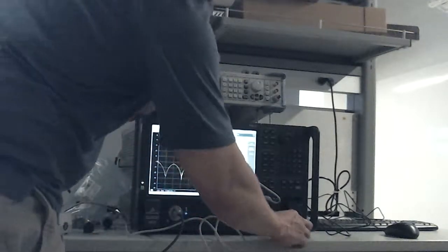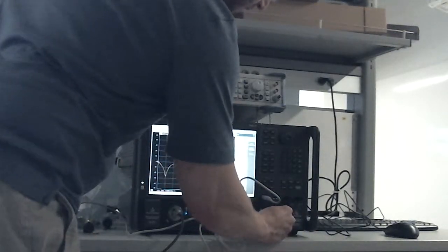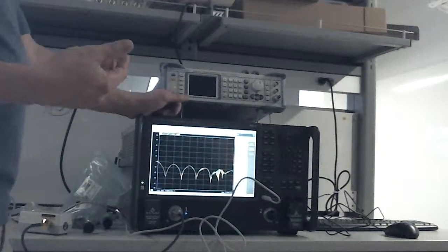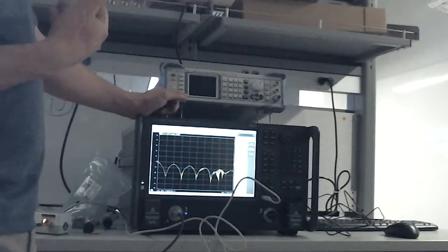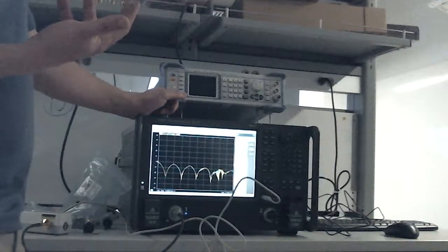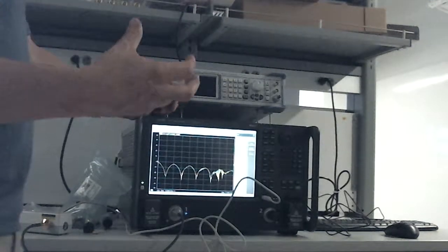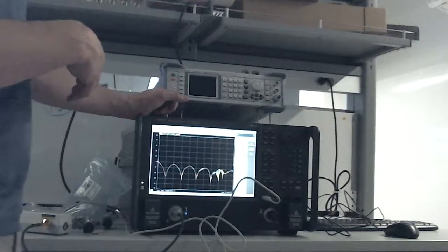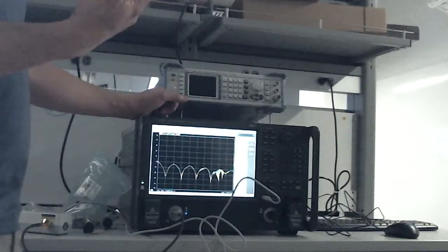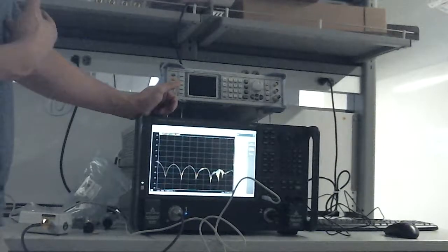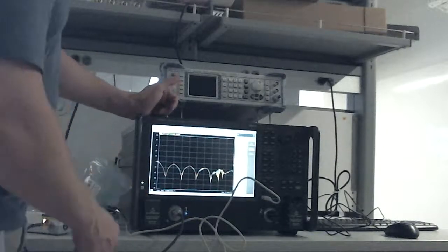One other piece of advice I give you is just to cover up your connectors. If you have the SMA bullets, it's not as critical, but I'd still recommend it. The reason for that is, especially with these high-end connectors, because the dielectric is air, if you leave it open, then dust gets in, and the dielectric is no longer air, it's air plus whatever dust gets in there. So that's something just to think about.